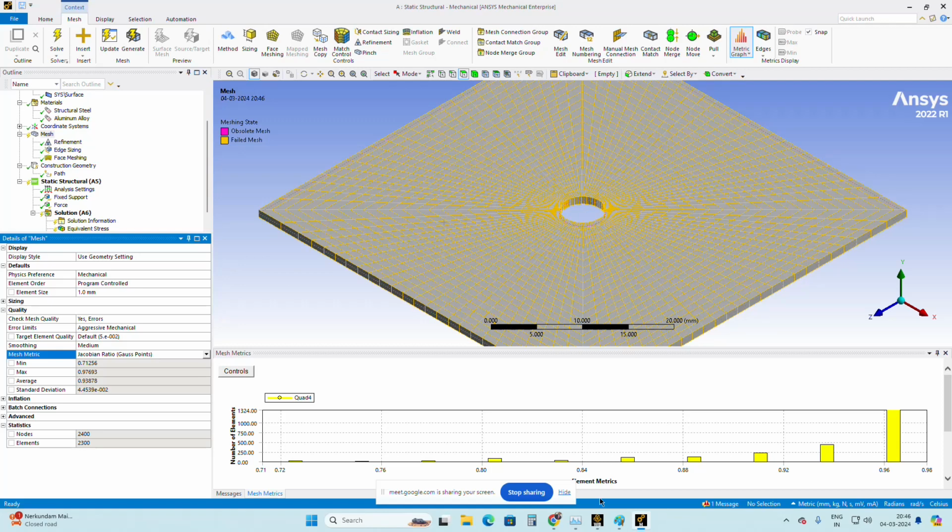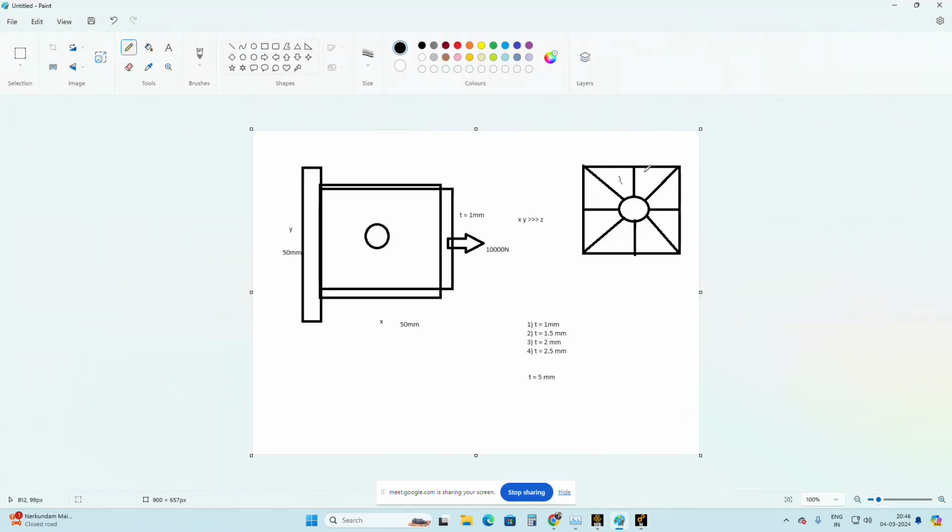So sometimes we have to go with manual meshing, where we split the structure. It is advisable to convert the parametrical surface into a biparametrical one, and then if you do the automatic mesh, you can somewhat minimize the errors in the structure.